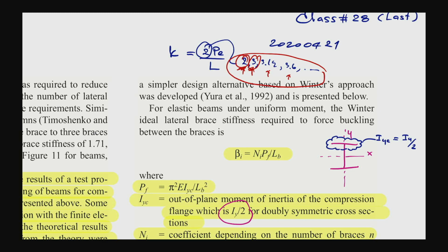And if you don't want to just believe in the number in the design, if you are stubborn like me, for example if you have multiple bracing points, like 7 points, and the number you get is between 3.6 and 4, you want to find a precise one. Well, 4 will be conservative, of course, but you want a precise one. You can play around with the codes like that, and you can come up with the optimal brace stiffness.